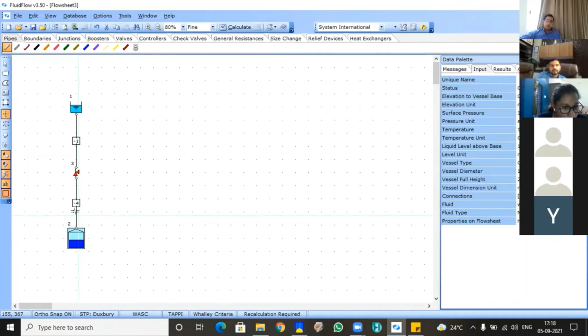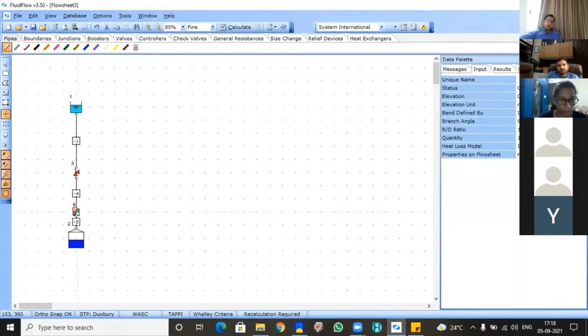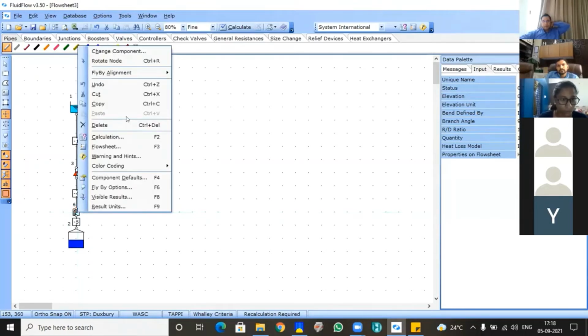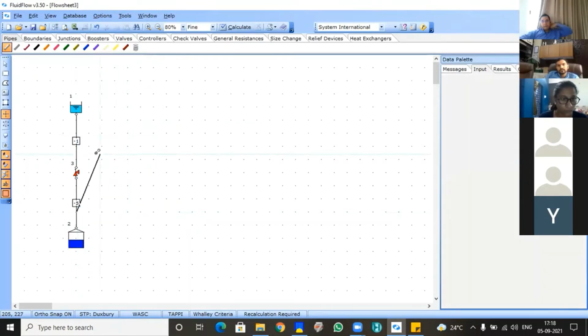Ma'am, this PSV is on the top of some vessel, right? So this gas is going to go from where? From the vessel to the PSV, right? And from PSV to this tank represents the PSV outlet condition. And this vessel represents the PSV inlet flange condition, right? So we cannot just have PSV as standalone. So that's why we have to provide this vessel and this tank.